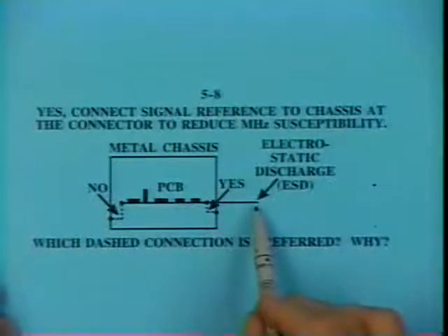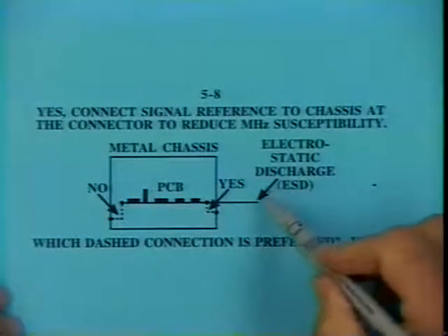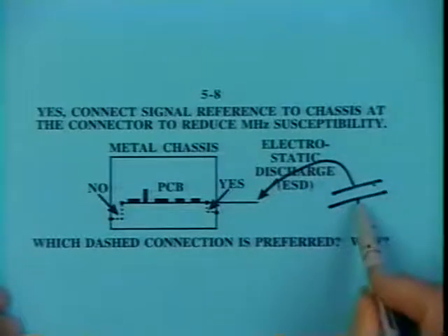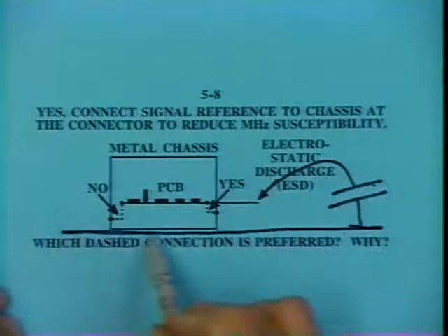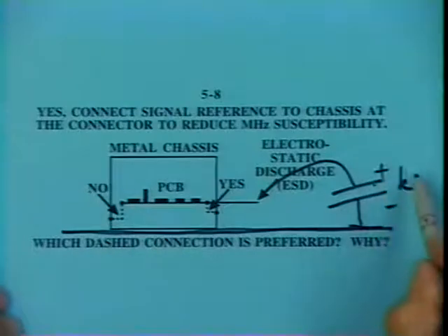Now you usually can't discharge to an insulator. You have to discharge to a metal, some conducting material. So maybe we're talking about the metal pin of the connector exposed, or maybe the end of the wire is somehow exposed. With the insulation around the wire, if it's adequately thick, we'll not be able to discharge through the insulation to the wire. But somehow the wire is exposed, and the electrostatic discharge can get access to the conducting surface. Let's think of the discharge as coming from a capacitor that is charged relative to a ground structure, several thousand volts.